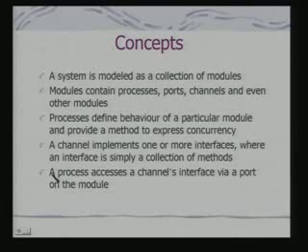So what are the basic concepts involved in SystemC? A system is modeled as a collection of modules. Modules contain processes, ports, channels, and even other modules. Processes define the behavior of a particular module and provide a method to express concurrency. A channel implements one or more interfaces, where an interface is simply a collection of methods. A process accesses a channel's interface via a port on the module.